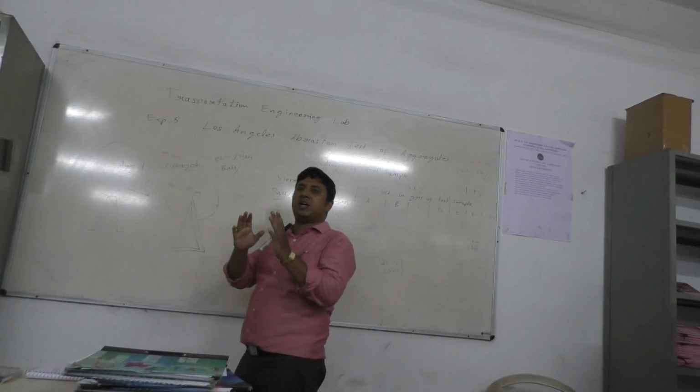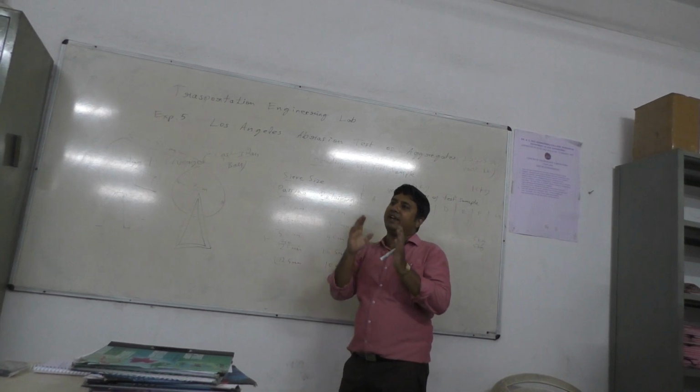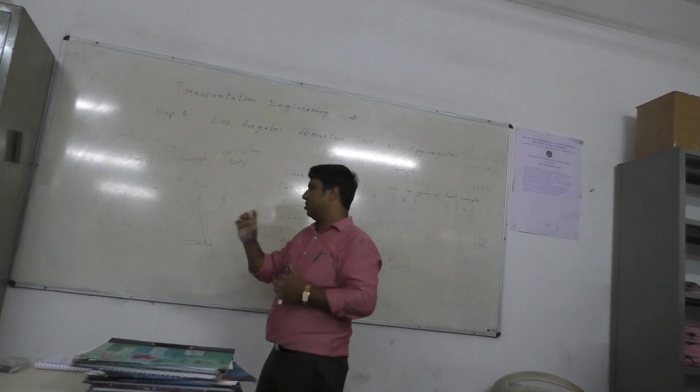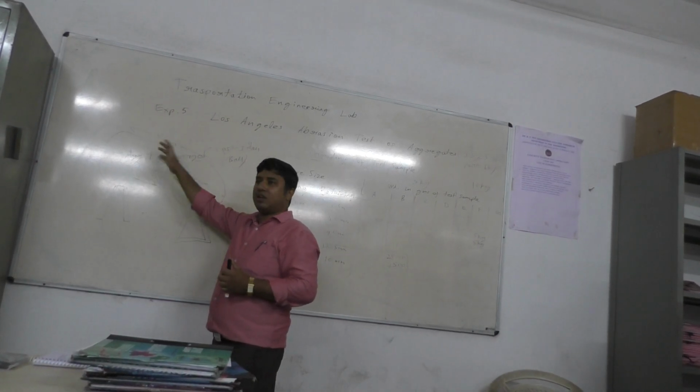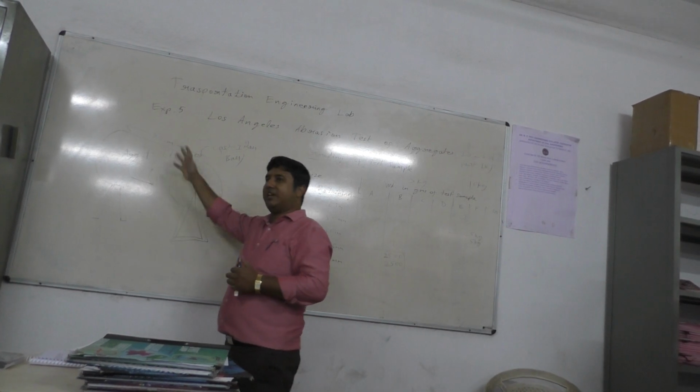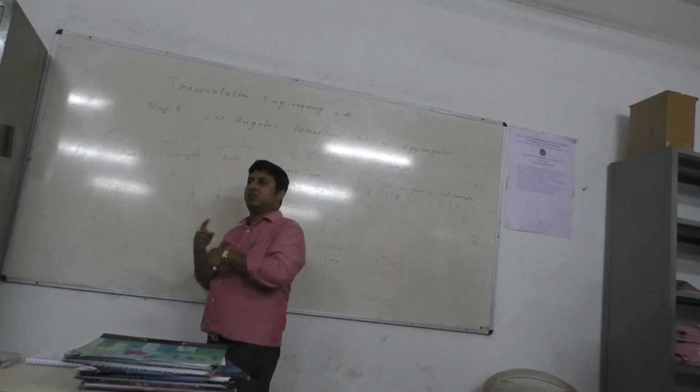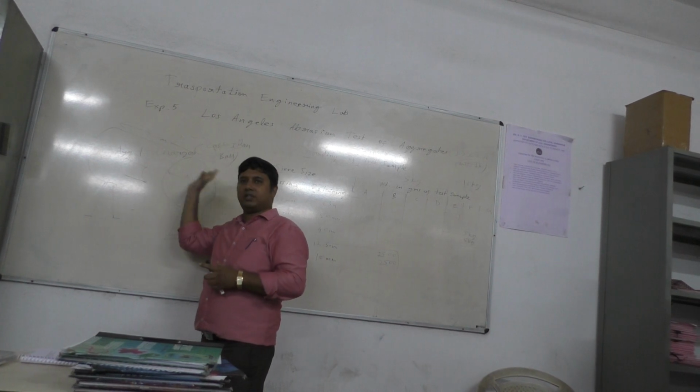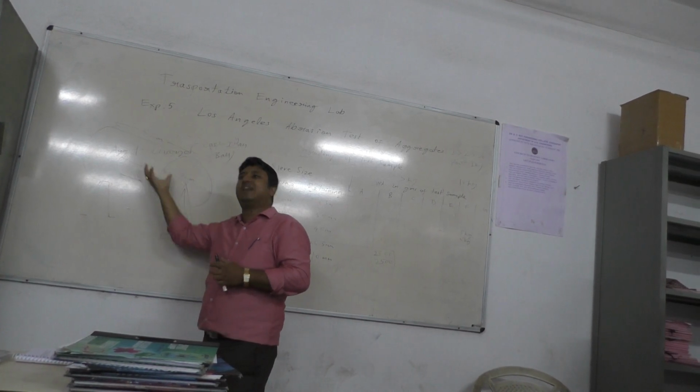The weight of each abrasive charge is 395 to 448 grams, and the diameter is 48 mm. Once it is put in, it will do the rotations. Once it reaches 500 rotations, when it is completed, then we will remove it.